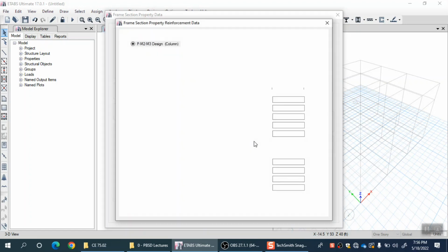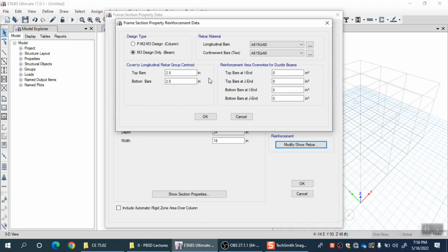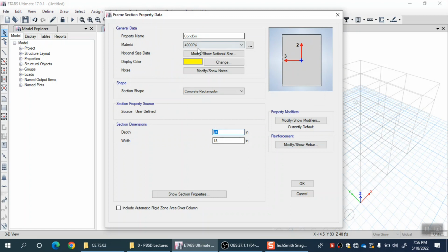So if you have, let's say, many types of beams, or a beam with the same cross section but many different amounts of reinforcement, then you have to define a different cross section, right? So maybe the same cross section and same material may be having a different steel, so you have to define a new cross section and assign it to those particular beams in your model which have that steel. Ultimately in your computer model, all beams at all floor levels should have a realistic reinforcement which will be there as a part of the final design, right?